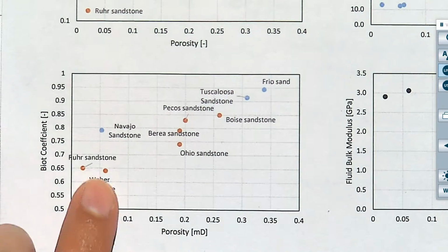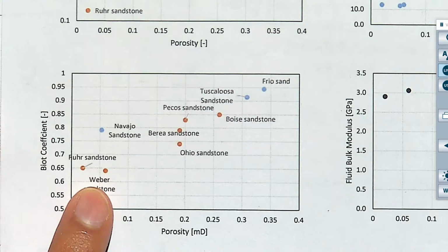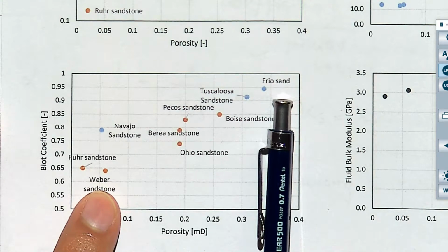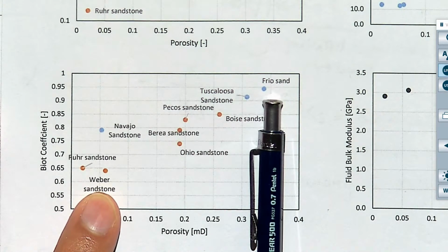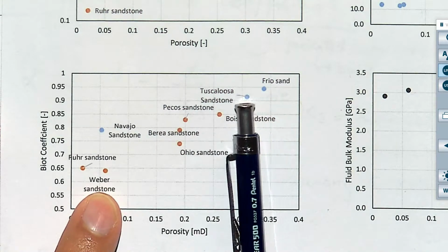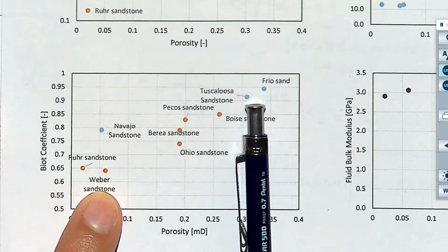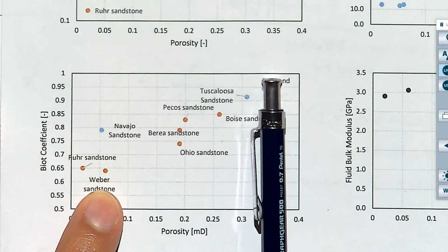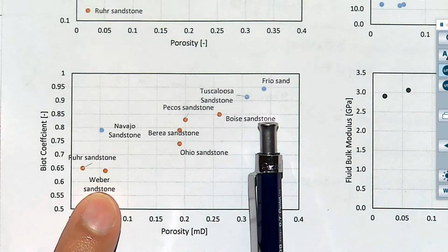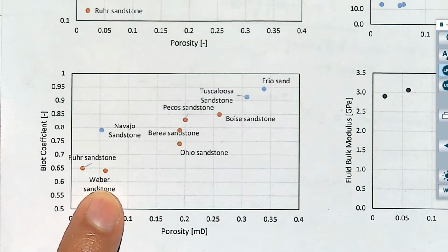One more thing over here, I just remembered that the Biot coefficient is many times assumed to be equal to 1. And when you have very porous rocks and you calculate the stresses, you could be making an error by assuming this equal to 1, of about 10%.